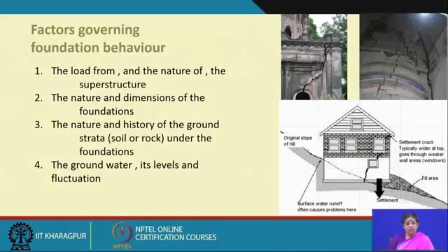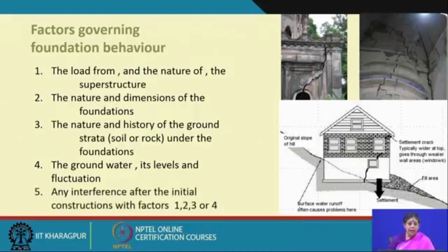The groundwater, again and again I am saying, the change in the groundwater level, especially in an urbanized area which was earlier not so urbanized, where development is happening and deep tubewells are being installed. The fluctuation of the groundwater level can cause a change in the behavior of the foundation. And any interference after the initial construction, any of these four, or a combination of them, can cause problems. So, these are the major factors which govern the foundation behavior.